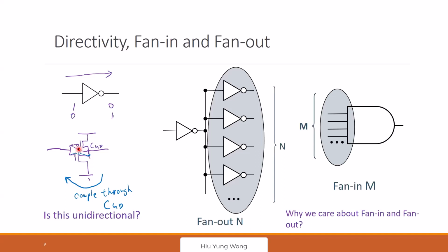You just say, oh, we have a deadline tomorrow. Let me just do a quick logic synthesis. I come up with a new great idea, save a lot of area, and also much faster. And you tell your boss, we don't have time to do more verification, the full chip simulation. Let's tape it out. And then you will be doomed to fail, because you did not do the simulation, and actually there will be backward coupling. I don't know how complicated your circuit is. You introduce something new, but you forgot about this backward coupling. You actually screw up the whole logic, right?